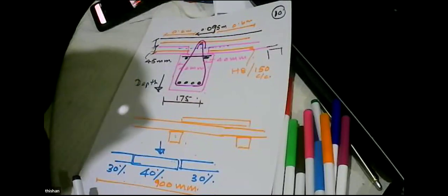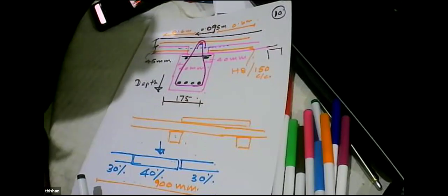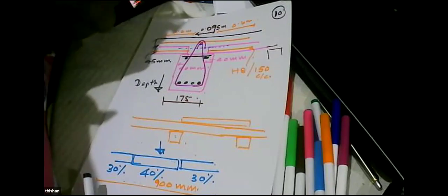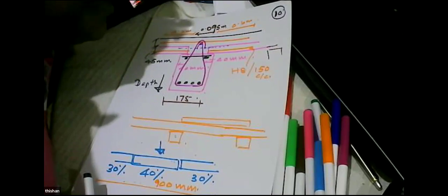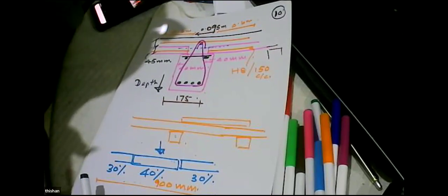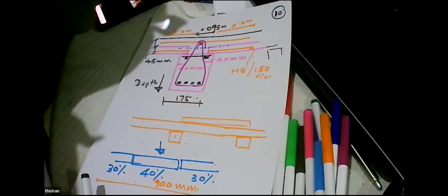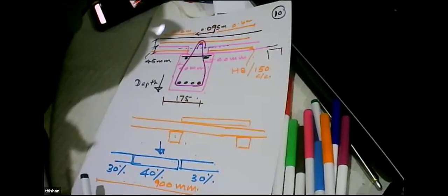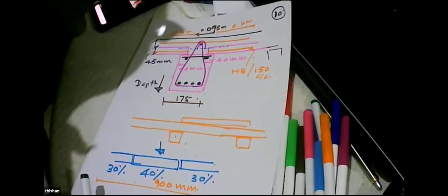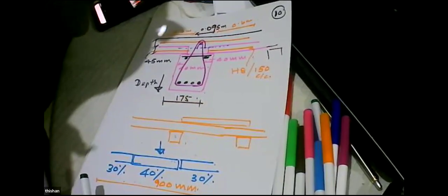Any other question? The last question was about the space between beams. Maximum 2 meter. Every 2 meter you have to have a secondary beam, which spans onto primary beams. So the primary beams can have any span, 4 meters, 5 meters, 6 meters, 7 meters, 8 meters. What you have to do is increase the depth of the beam if the span is large.